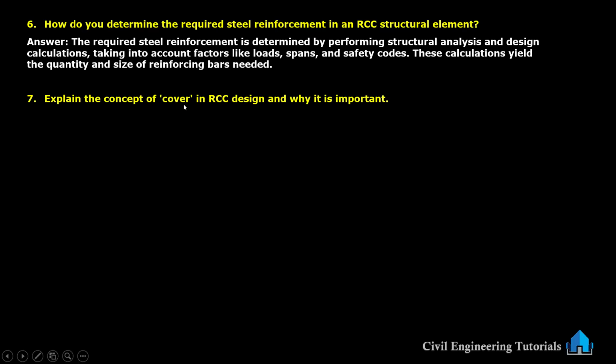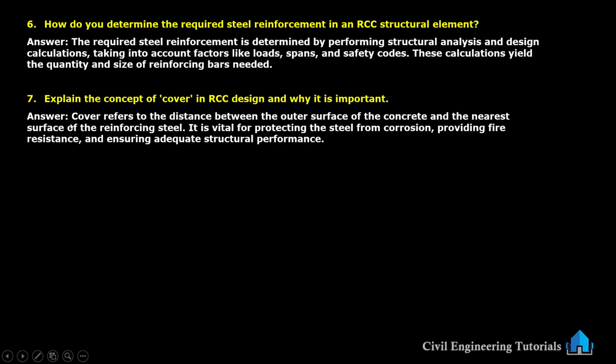Explain the concept of cover in RCC design and why it is important. Cover refers to the distance between the outer surface of the concrete and the nearest surface of the reinforcing steel. It is vital for protecting the steel from corrosion, providing fire resistance and ensuring adequate structural performance.